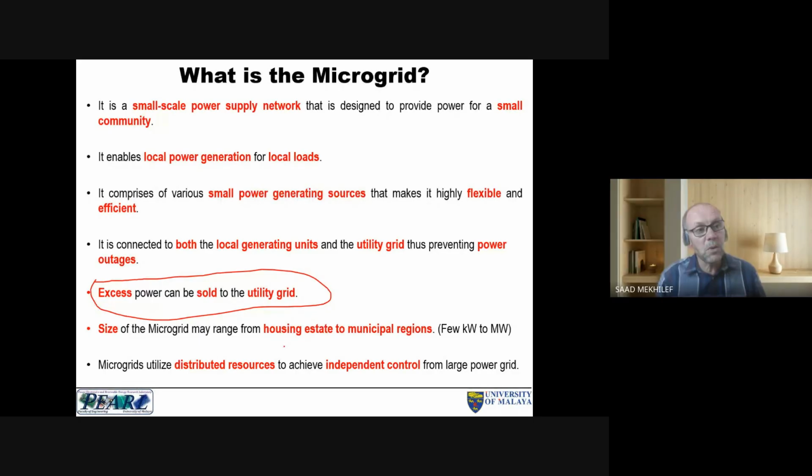No, picogrid means talking about something less than 5 kilowatt, or less than 10 kilowatt. Microgrid, you're talking about a few kilowatts and above. And the operating voltage depends. We can operate at 48 volts, we can operate at 120 volts. But if DC, most of them we operate at either 48 volts or 96 volts.